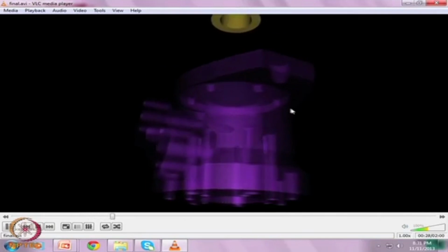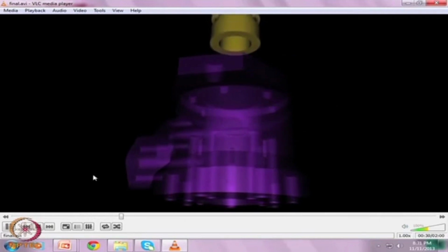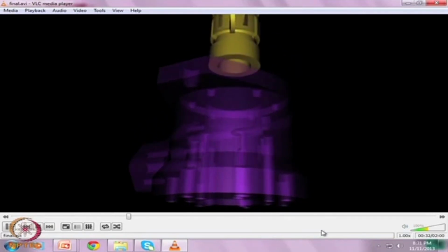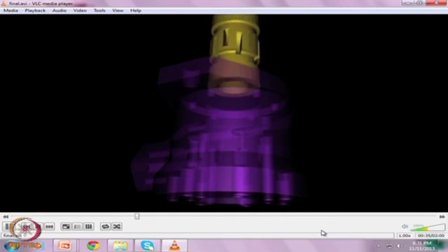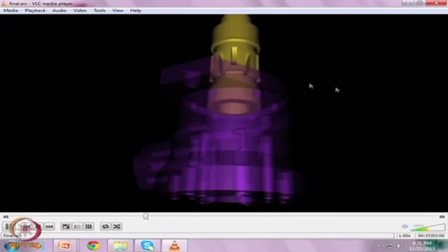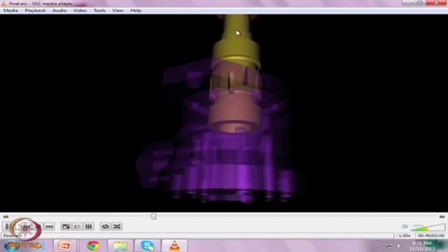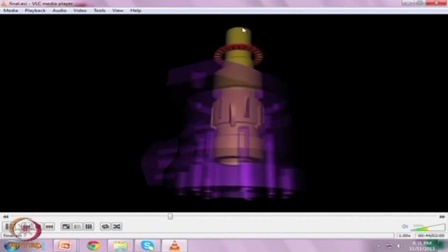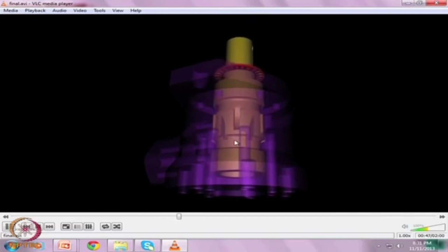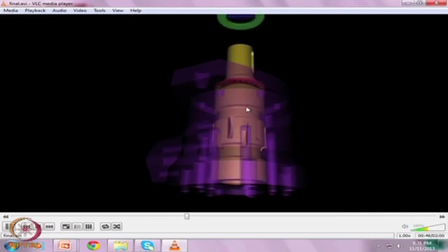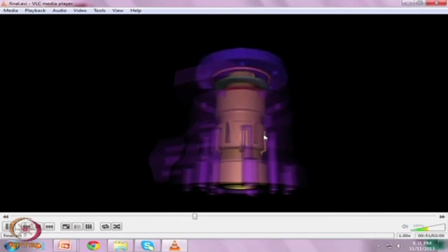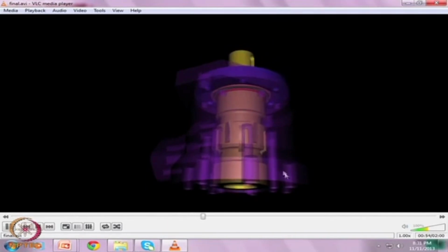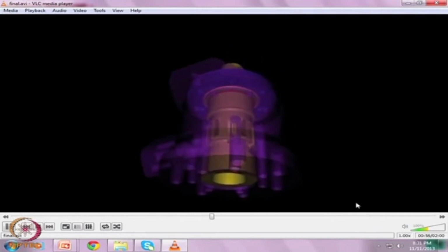In case we find that this body is being used as an output, we have to connect this input and output oil maybe through this shaft. It is possible in this shaft from the front side, which will be held, we can make two grooves, and we can make a hole here and here. So, it is possible, or I mean it is not difficult.